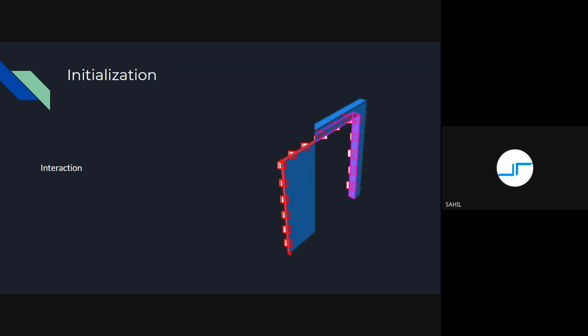Now the interaction part: the surface-to-surface contact type is used in Abaqus, and the sliding formulation is finite sliding, in which there is a small friction between the masonry wall and the frame, and the load is also transferred to the masonry wall.